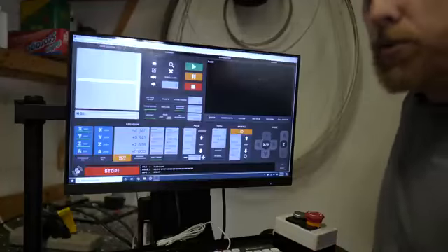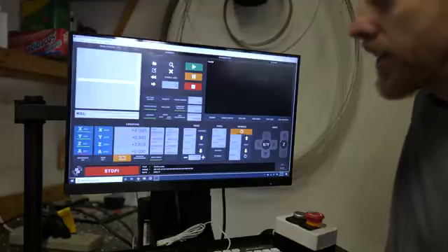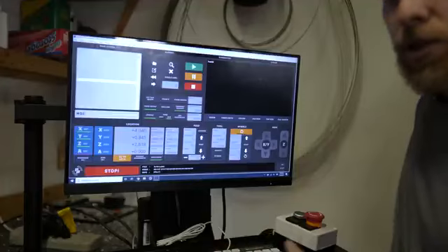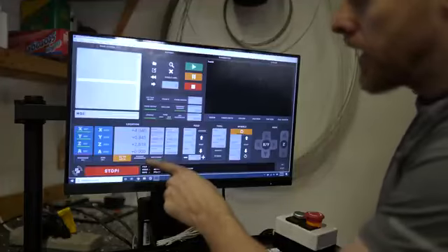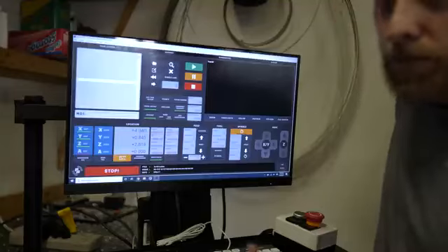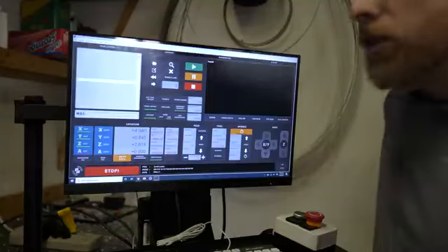So I'm still working on that. I think there may be a system to do it. I just haven't set it up yet. So when I turn on the machine, it homes itself. It stays in its 000 machine coordinate position, and I hit reference all, and it automatically sets them to 0, as opposed to homing the machine. That's what the reference all usually does.